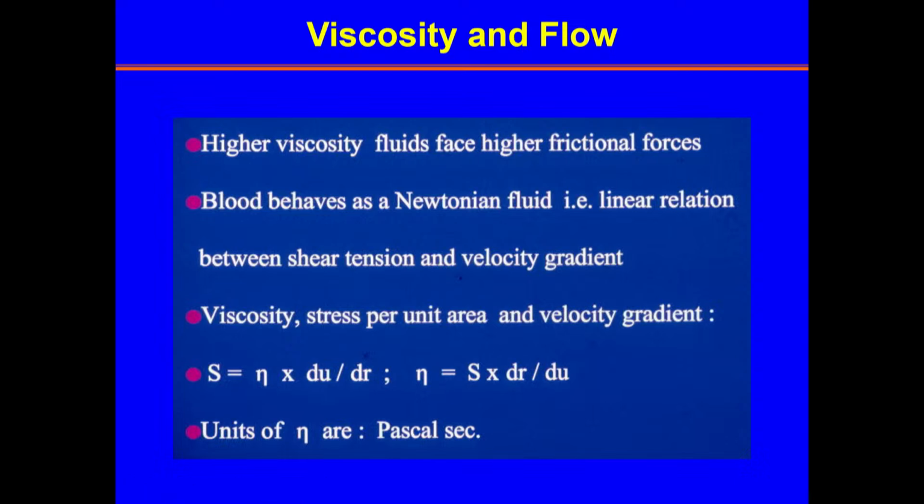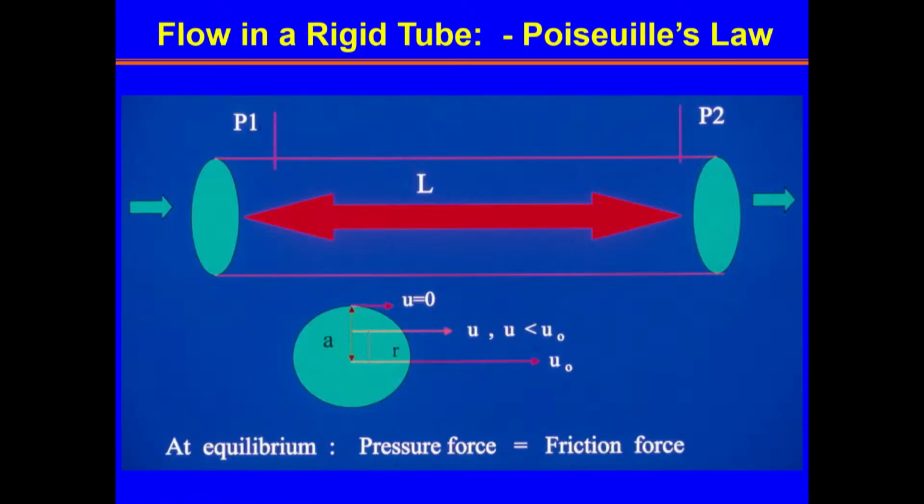We are interested in knowing what the units of viscosity are, so we rearrange that expression, and now you will see the shear tension, which has the same units as the pressure, so we will put that in Pascal. And if you look at that, it's distance divided by velocity, so you end up with the product of Pascal and second. These are the units of viscosity. We want to remember that as we go through other slides later on.